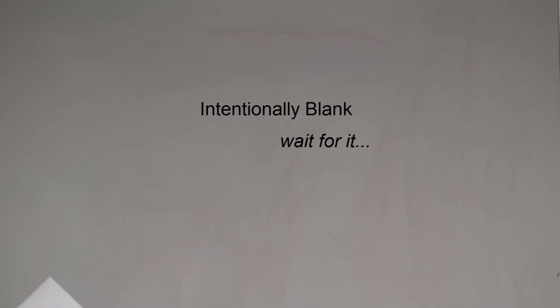Okay, so now it's school time. The instructions tell you that to enable filter mat monitoring, the display should be set a minimum of 10K above the temperature difference shown in the program. Filter monitoring is disabled when the code is 99. So 99, which you saw, tells us it's off.